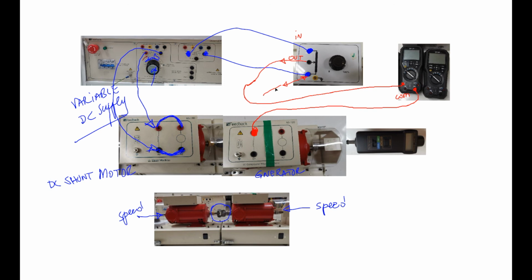Now the ground, sorry, this part here, goes over this wire and supplies the minus, the negative terminal of our winding. So the current will come from out here, go through the ammeter, come back from the ammeter to the winding, and from the winding close the loop and go back to our ground here.